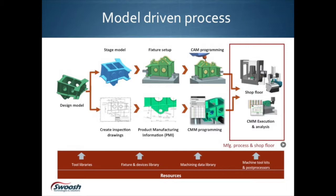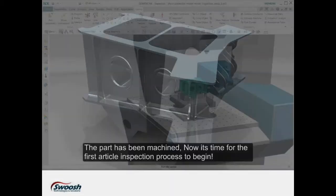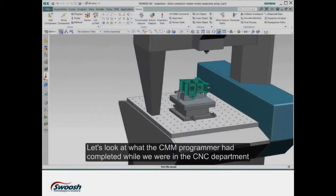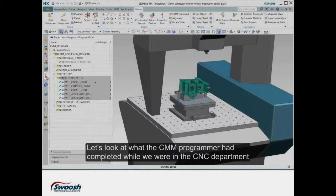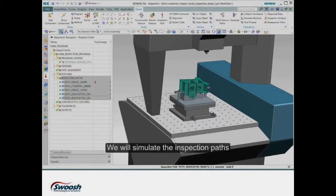Here, Brian will use NX to simulate what will occur on the shop floor. The part has been machined. Now it's time for the first article inspection process to begin. Let's look at what the CMM programmer had completed while we were in the CNC department. You can see the inspection paths now have been selected and are completed. Any modifications made, we'll now go back and simulate what is happening on the shop floor inside of NX CMM.